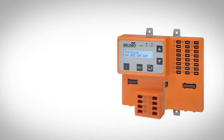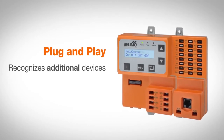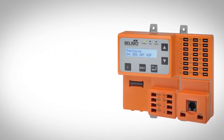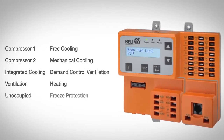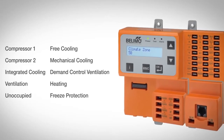In fact, it's even plug and play, so it recognizes any additional devices you might have, like a CO2 sensor, and you can just as easily monitor all the parameters in real time. From the status line, hit any key and the Monitor Live Conditions submenu displays, where you can view the changeover setting and climate zone configured by the zip code, as well as other live conditions.